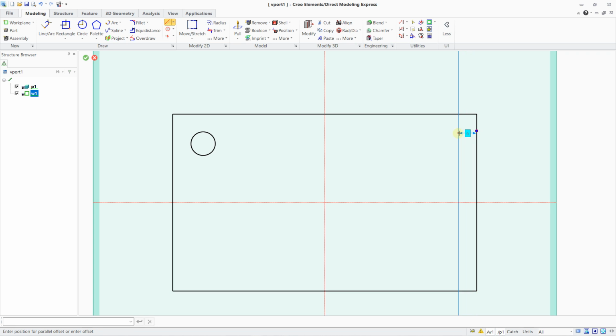I can click on this line and drag and move at 10. I can press escape, reuse parallel, click on this line and apply 10, just like that. Thanks to that, I have a guide and I have my center point here. I can create a circle and do this process again with 6 mm or another value.